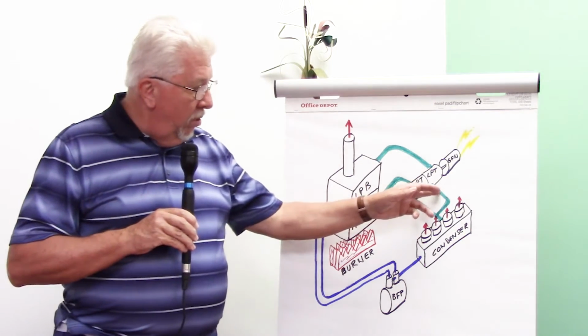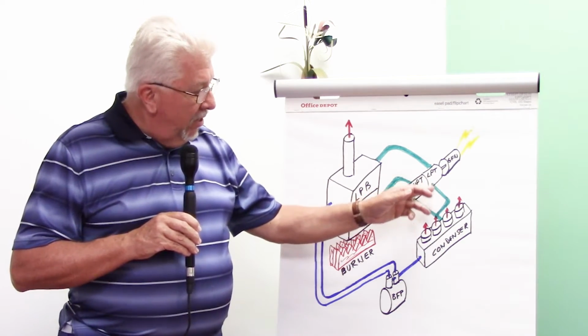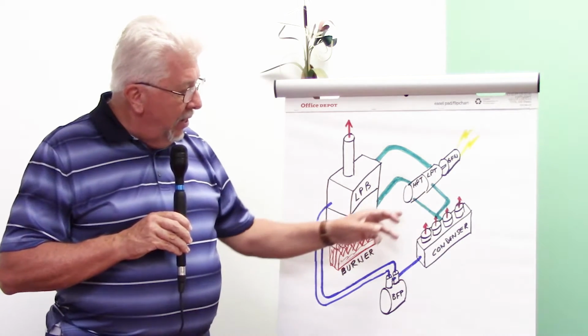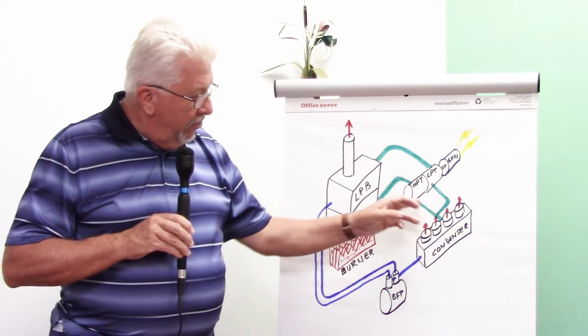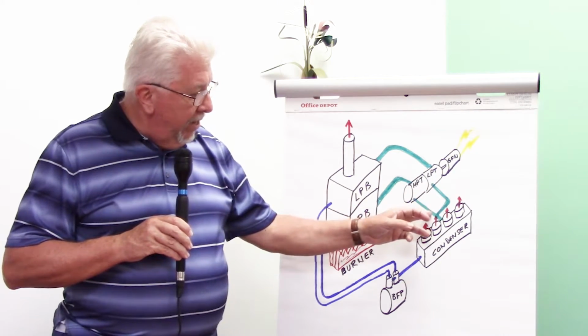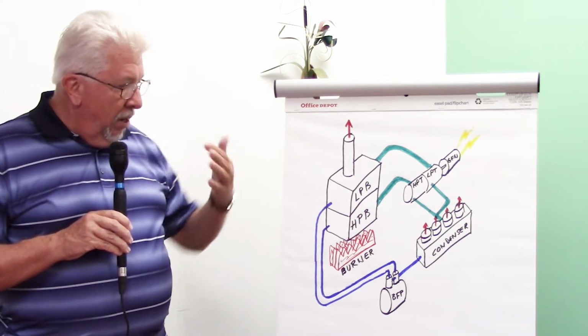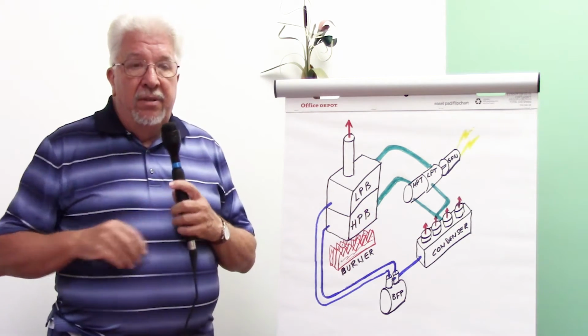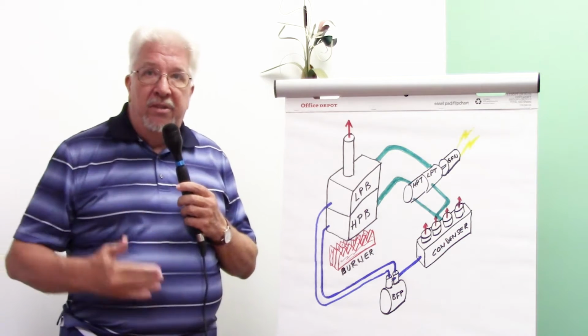All right, that's where these operate, and that means that the temperature coming off here is around 200 degrees Fahrenheit, and the temperature coming off here is around 200 degrees Fahrenheit. Okay, and the pressure is around 5 psi, which is below atmospheric. That goes to the condenser, which takes the vapor and condenses it back to liquid.